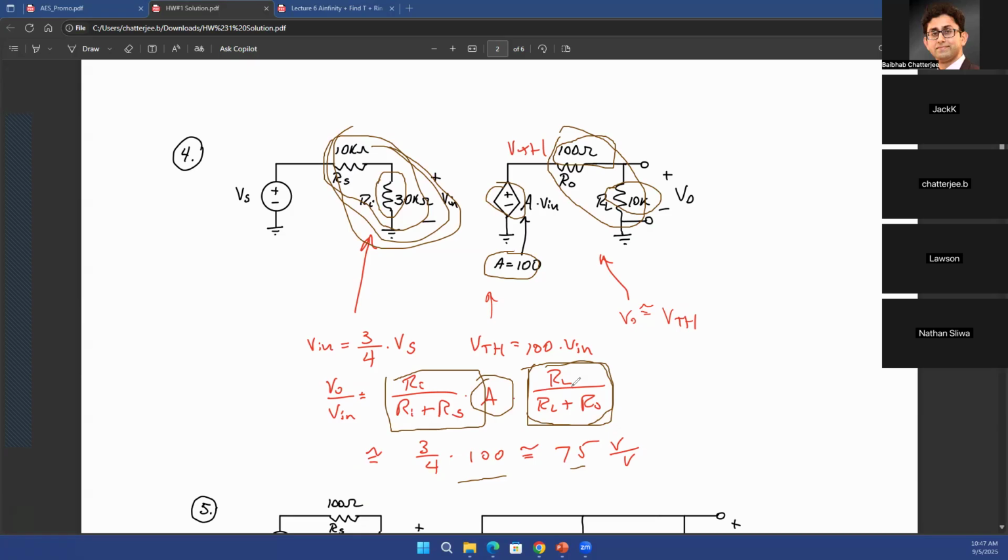So it doesn't make sense to spend a lot of time figuring out what that exact ratio is. If it is very close to 1, write it down as 1, because anyway in your components, you may not find anything that is exactly equal to 100 ohms. You may not find anything that is exactly equal to 10 kilo ohms. So it doesn't make sense to try for that degree of accuracy when you're solving the math problem, because in real life, it will not be as accurate.